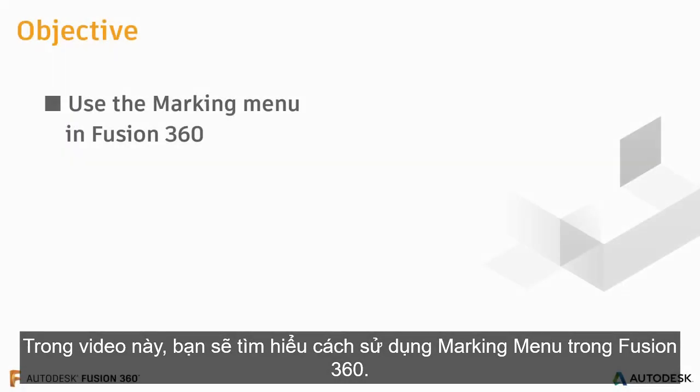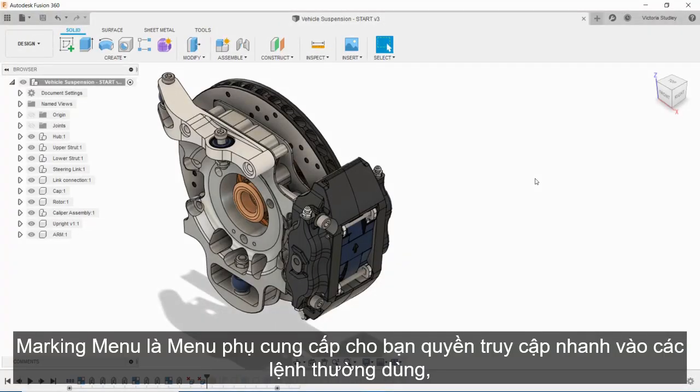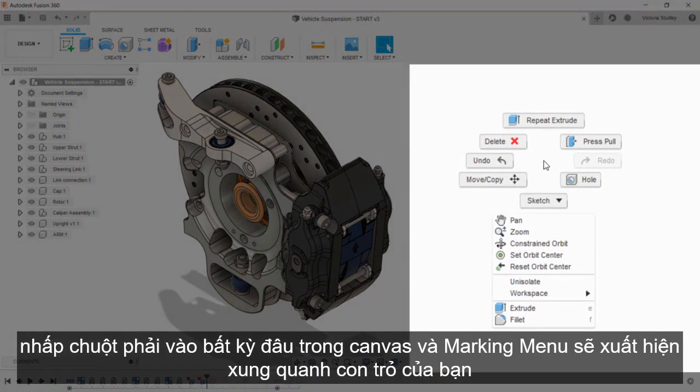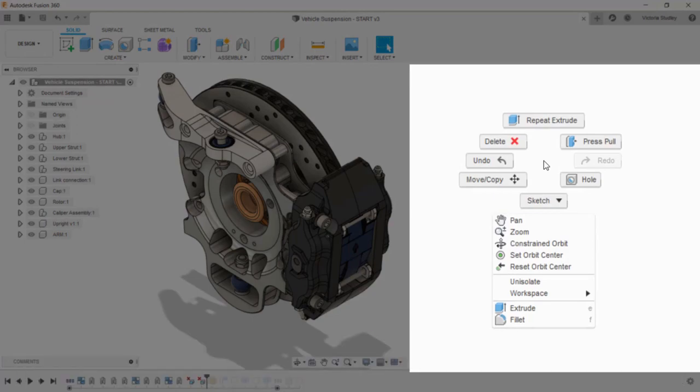In this video, you'll learn how to use the marking menu in Fusion 360. The marking menu is a radial menu that provides you with quick access to frequently used commands. Right-click anywhere on the canvas and the marking menu will appear around your cursor.